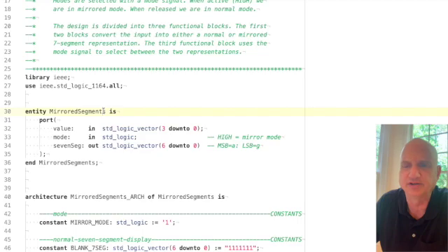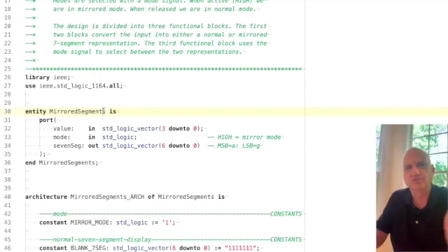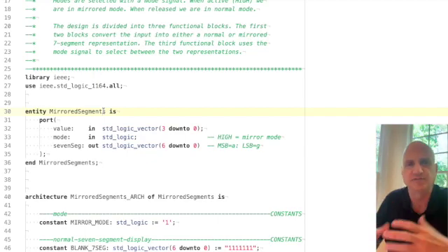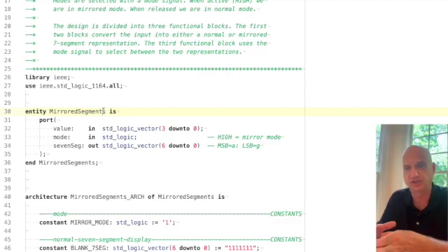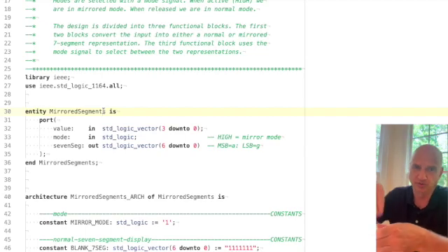You really need to design your components to be independent of any hardware, any board design. To do that, you would isolate your component, give it the names that it needs, and then embed your component in an external component that's simply designed to do the interfacing for you. I tend to call that my chip, so that it emphasizes the fact that this is an actual FPGA chip that you're interfacing to. And then inside my chip, we'll put our design.